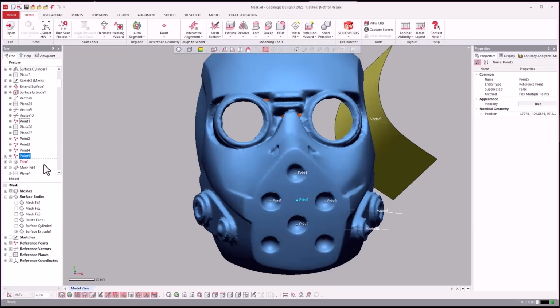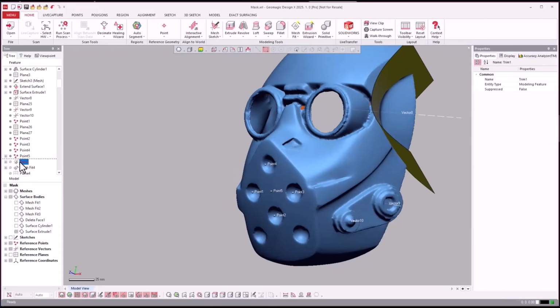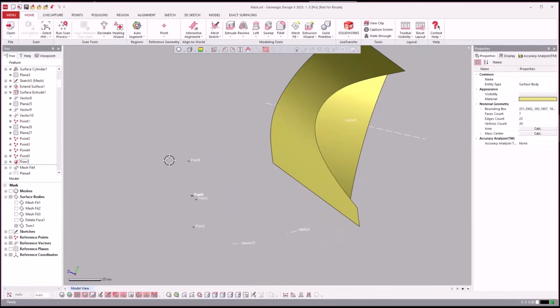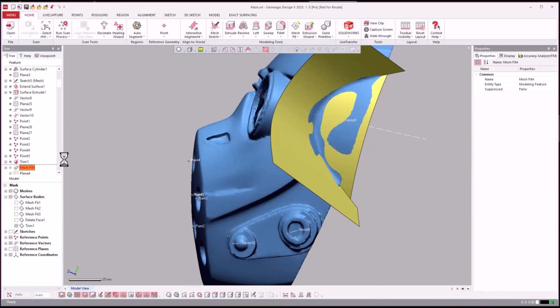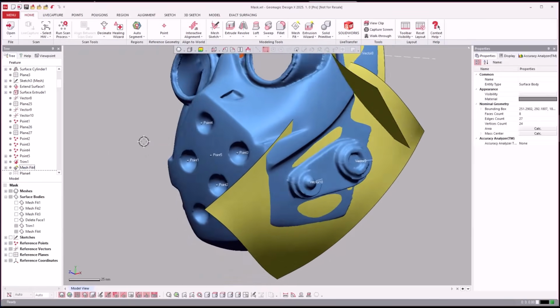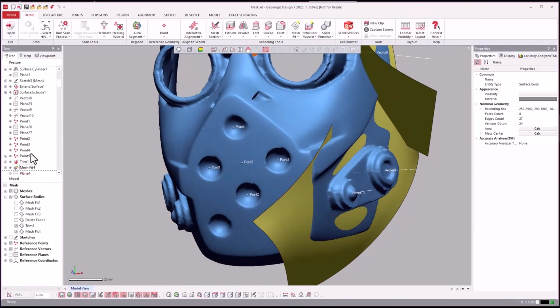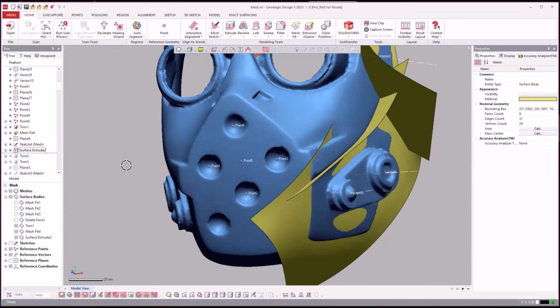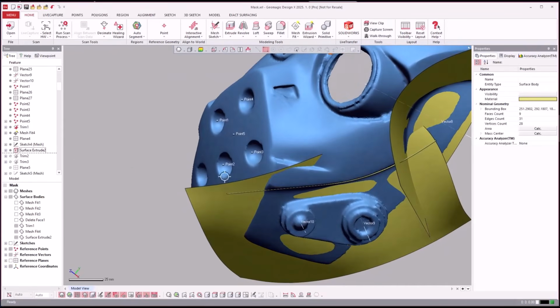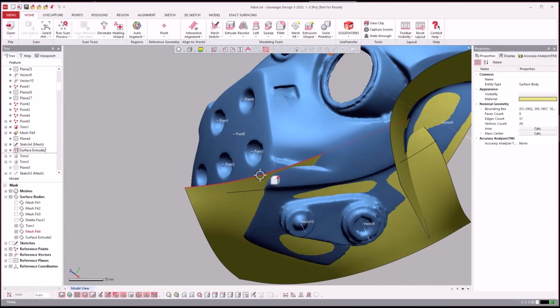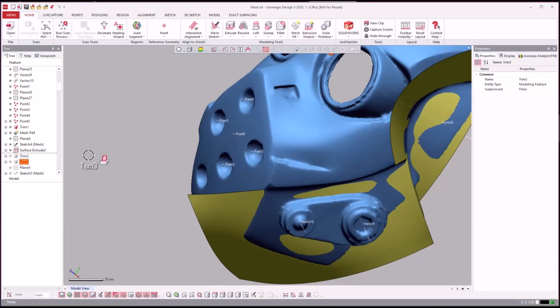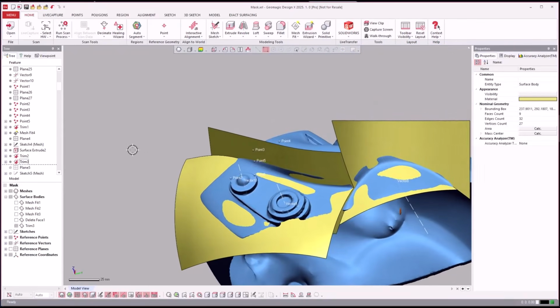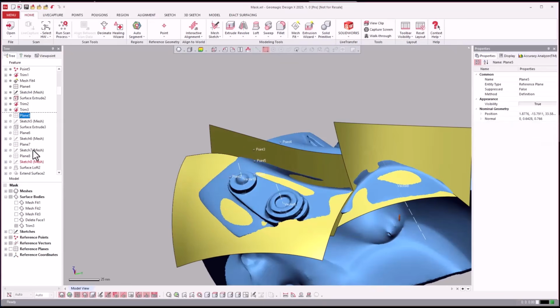So now let's go back. So there is our surface. We went ahead and trimmed those two together. Looks like they do a mesh fit down here on the bottom side of the jaw. We did another one in this direction. Again, we could have calculated that manually or just looked at it in this direction and created a plane. Now they're going to trim those. Trim all these pieces together.